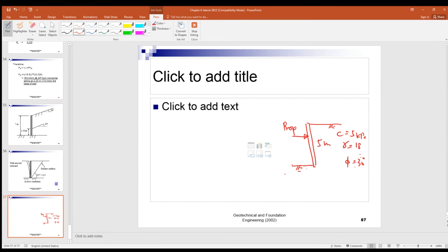So by theory you can calculate this. You have the Ka, gamma Z, and so on. So you get the active pressure, pointing towards the left, and then you can work out the force here, acting in the opposite direction. Suppose, according to the earth pressure theory, you work out 100 kN. So you are happy with that after very careful calculation.